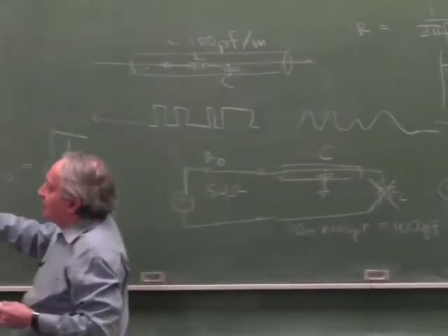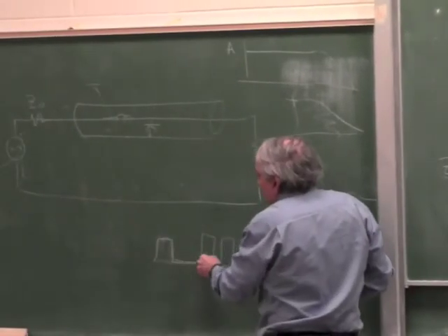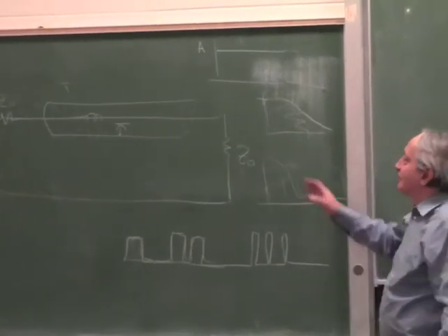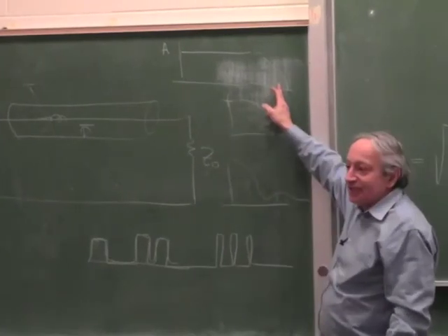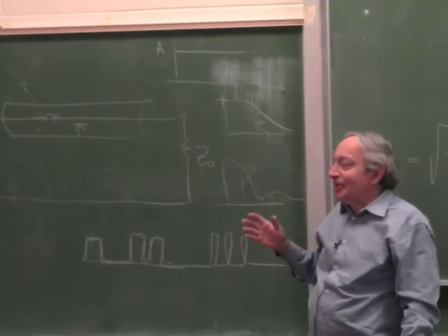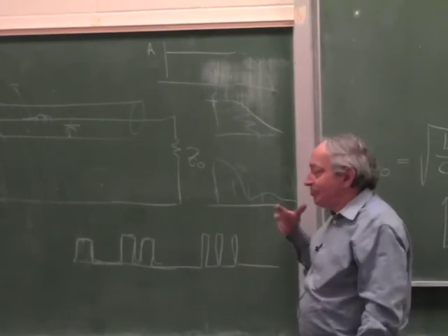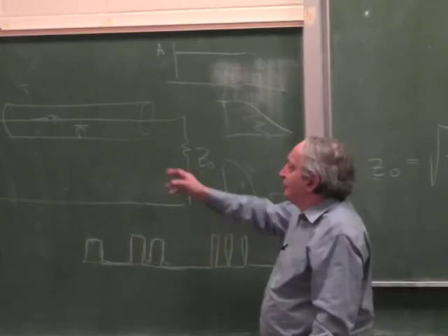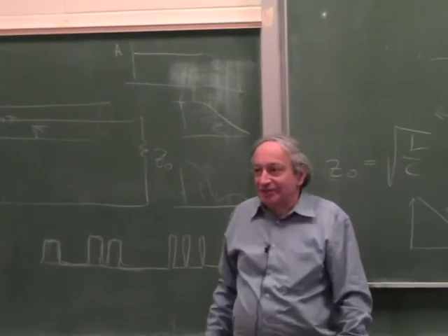Now if I send a pulse train through this, it will come out exactly the same, maybe with slight rounding because it's not infinite bandwidth, but basically the same. So the significance of something being frequency independent is not just that you can work at high frequencies, like in RF. The real significance is that it doesn't distort the shape of the signal, because it passes all spectral components equally. So that's why when you send pulses over long distances, and not just pulses but high frequencies, you have to use this method, like a transmission line, versus just a shielded wire.